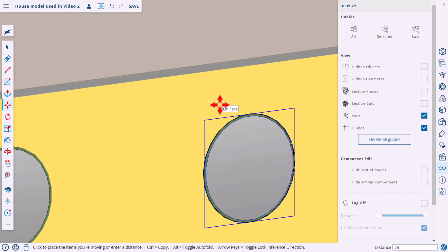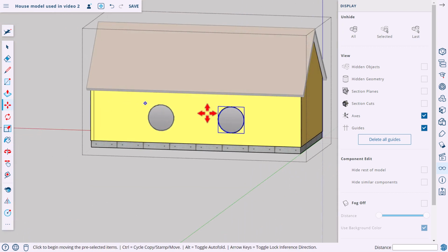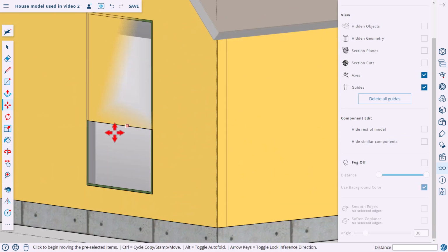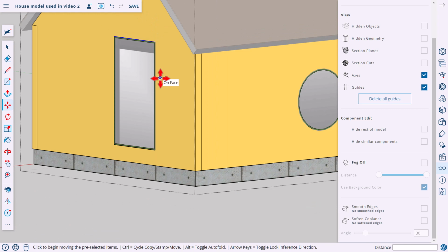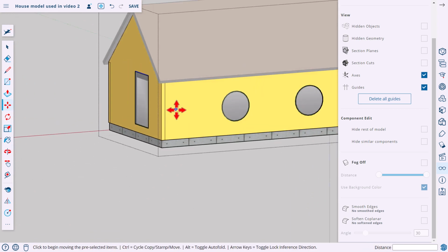And this is the nice part about always drawing with axes, is that you can quickly move things and get them right back in the correct position very quickly. The other thing is here I've got my frame. Remember I drew that rectangle, but it was too small. I can just move the frame edge, the opening edge up, and I'm holding down Shift to keep it going in that vertical direction. And now you can see we've cut away the building correctly.